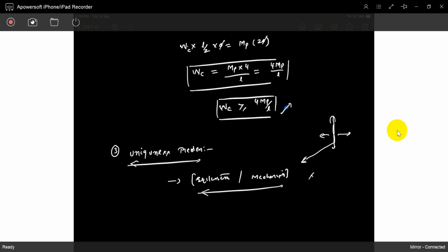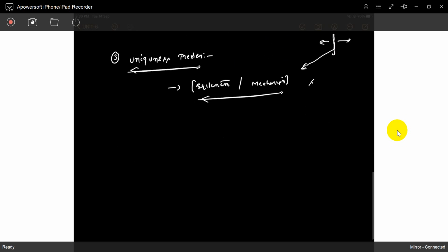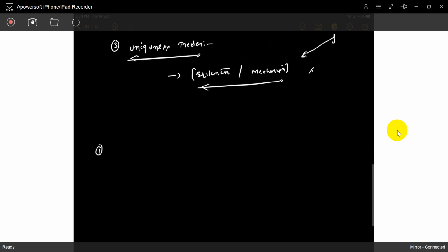I will show a very simple problem. Same thing. If it is a simply supported beam, see, a simply supported beam is a determinate structure. DS is 0. You require the number of hinges DS plus 1, which is 1. Understood? Once one hinge is formed, the beam enters the mechanism state or the collapse state. So that's all that is required. We will first do this type of very simple problem.